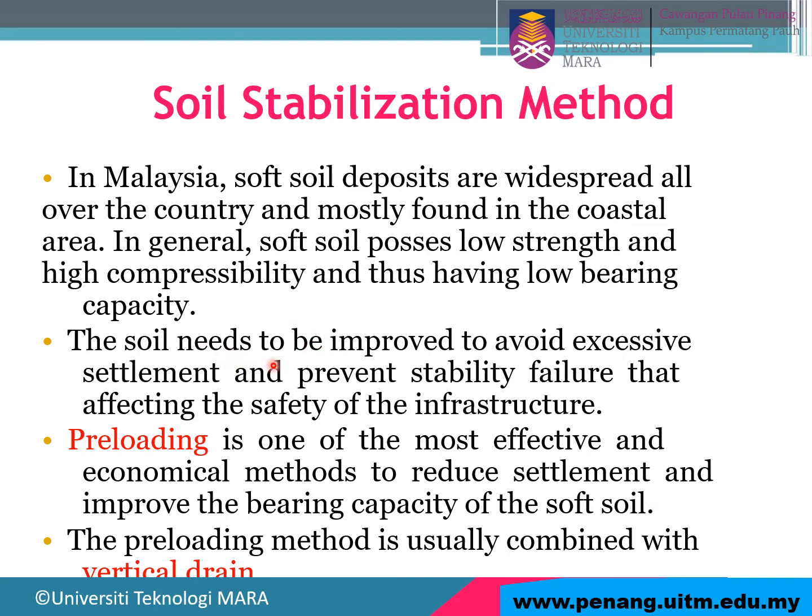So, the soil needs to be improved to avoid excessive settlement and prevent stability failure that affects the safety of the infrastructure. One effective method for soil stabilization is preloading. This is an economical method to reduce settlement and improve the bearing capacity of soft soil. Usually the preloading method is combined with the vertical drain.